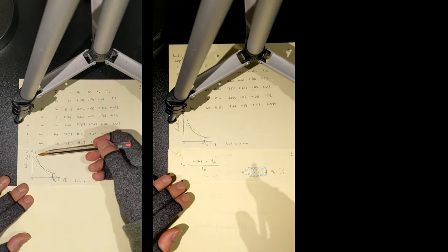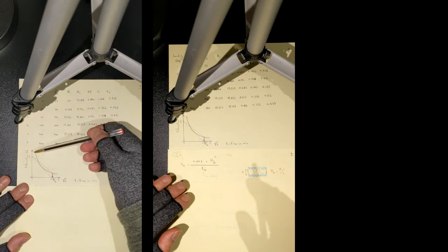On the vertical axis, you have deformation, delta H, in millimeters. And on the horizontal axis, you've got time. For this test, you've got 6 loading steps, so you will have 6 of these diagrams. Look at this. The red curve is showing the variation of deformation with time.